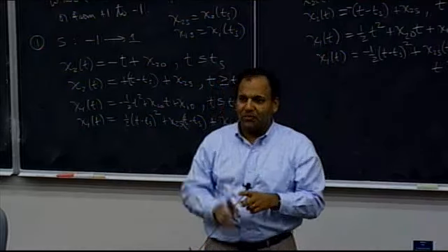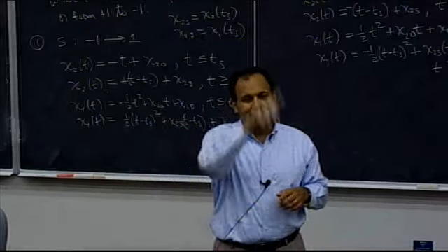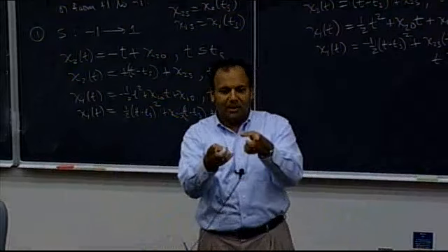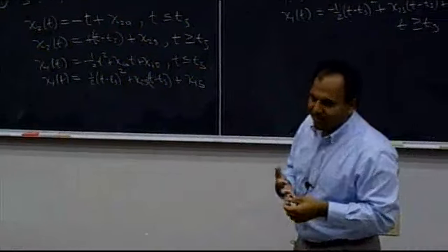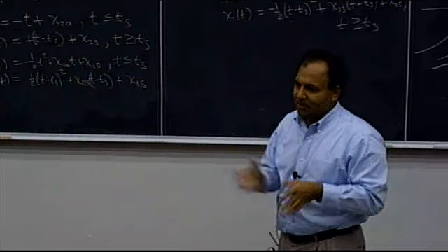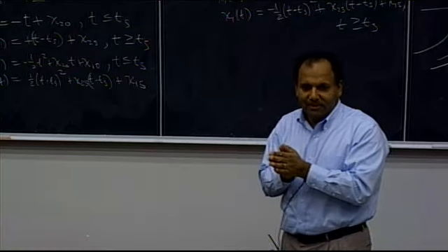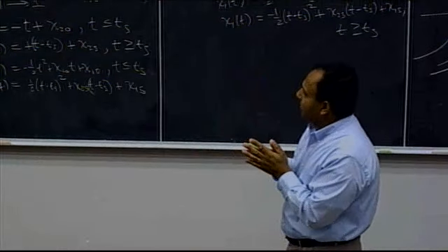Most people, when they did that problem originally, thought it was a bang-bang control that went from max to min because you would fire the thruster and then turn it off. Turns out you don't fire the thruster and turn it off. You fire the thruster, then you fire the thruster in this really strange way, and then you turn it off. And that strange way is a singular arc. So we'll talk about singular arcs in a couple weeks, because it's a really interesting thing, and they're very, very difficult to deal with. But you need to at least see what goes on with singular arc problems. So we're done with the minimum time double integrator.